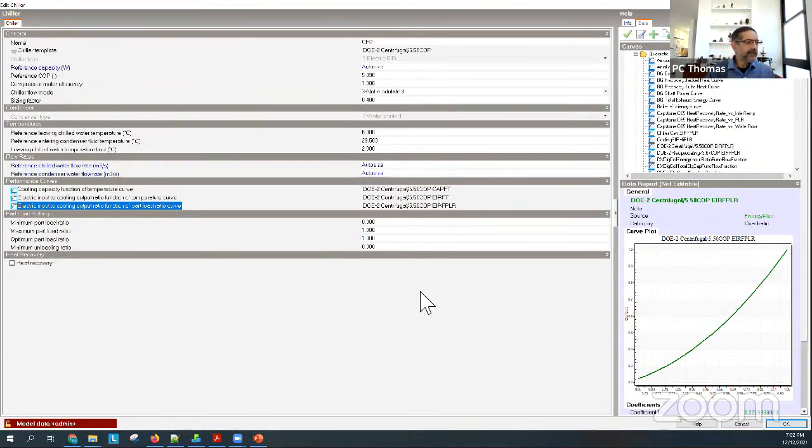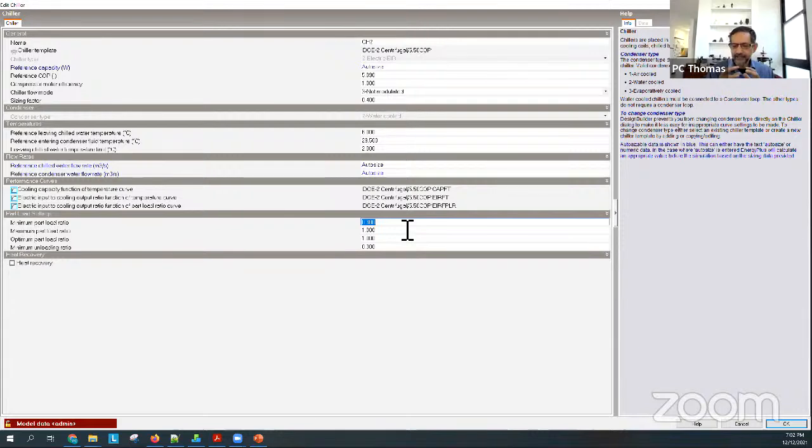Then these 3 are quite important. Okay, what is the minimum of its capacity that the chiller can run at? Now most manufacturers will tell you, oh, 10%, no problem. Okay, at 10%, the COP is horrible. It's using something called hot gas bypass. They never tell you that. Okay, so you want to talk to some practical engineers and they'll tell you, oh, I never run a chiller below 20% or 25% or 30%. Whatever it is, put it. Okay, I put 30% here, but modern chillers, you can go down to 20% quite easily.